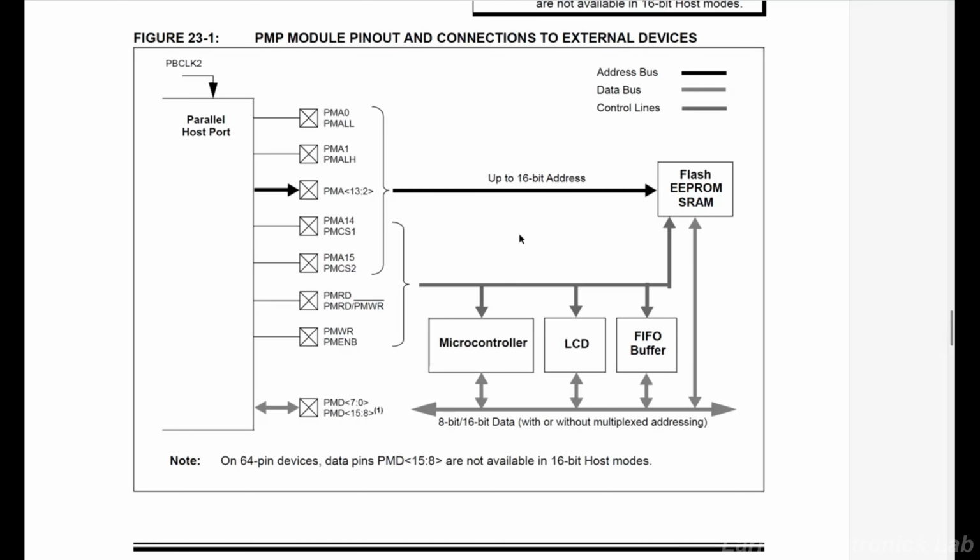So when you write to the parallel main port, it writes data out onto the bus and sends the proper signals. And you can program the polarity of your chip select and your read and write strobes for active high or active low, however you wish. So that's the advantage to that.